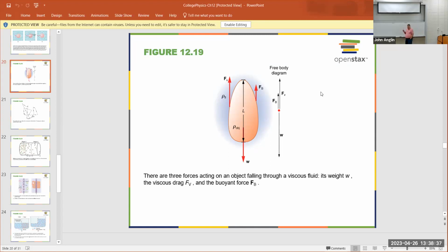So what we do is we build the spacecraft in such a way, generally these kind of cone shapes, where we create a bunch of drag. We create a bunch of buoyant force. Well, of course, we're trading energy, right? So we're going to turn that energy into heat energy. That's why it gets very, very hot. But what happens is we slow the vehicle down.